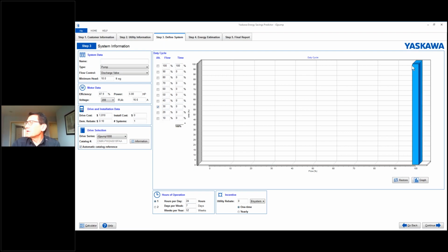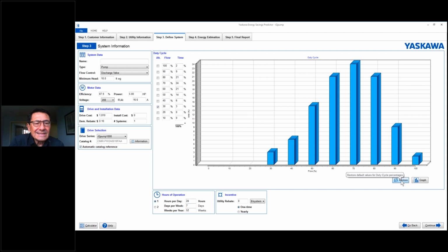Now, this is a 100% full speed all the time curve. Here, you will get no energy savings using a drive. Actually, what you will get is the efficiency. You'll get the cost of the drive and the drive's inefficiency, which typically is going to be about 3 or 4 or 5%. So the drive will actually cost you money with no return on investment.